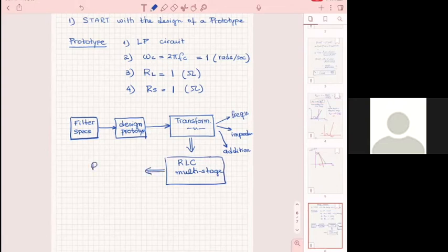So you have to go through realization, which means what? If my frequency is high and I'm telling you that we are working with microstrip, you will have to realize all of the R, L, and C using microstrip or a CMOS fabrication. I may tell you that I am on gallium arsenide and I'm working with coplanar waveguide. We're not going to do it for this class. But if you are an engineer out there, they will come and tell you the whole layout in all of our circuits is a coplanar waveguide layout. You go and design this filter, it has to be on coplanar waveguide. So this is the last part you do in the realization.